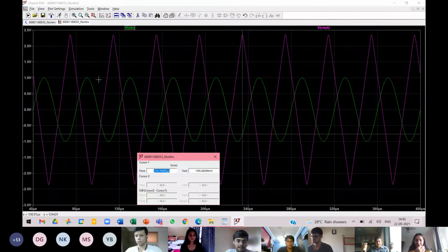All right. So wherever you see that the waveform has gone from your original signal to something like a ramp waveform, it means that this is the final point beyond which I'm not supposed to take my signal, right? So that defines the bandwidth in which your signal can play. And ideally you would always want this bandwidth to be as large as possible so that you can amplify signals of different frequencies, right?